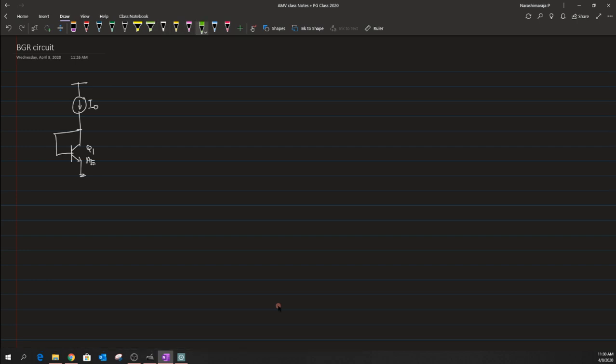a second branch of the circuit where it is again passed through not just the diode connected structure, but we also pass it through a resistor carrying a resistance value of R1, and which is then passed on to an NPN transistor with an area which is n times greater than the area of Q1.